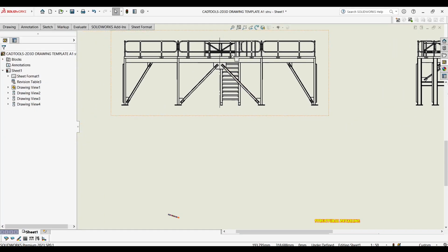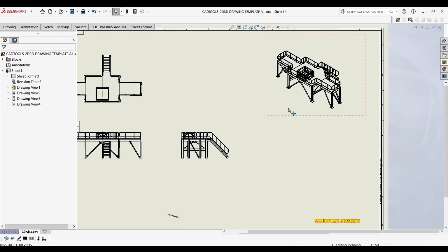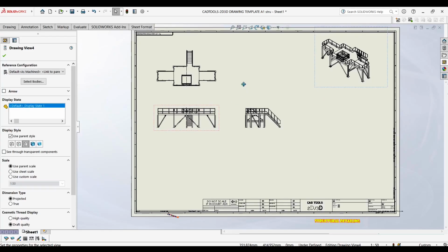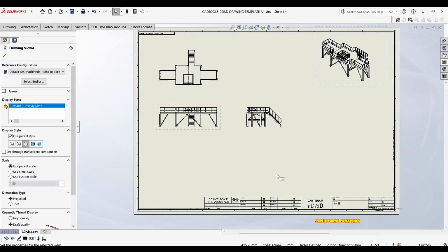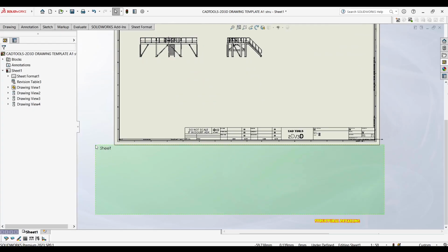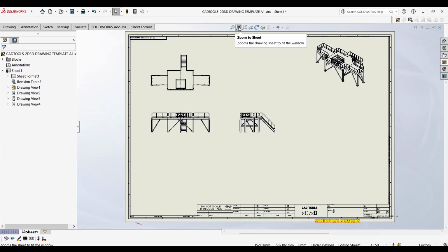and then guys, sorry if I became a bit louder, we have to now try to make these views a bit more visible. So with your mouse wheel, double click it. When you double click your mouse wheel, or you click here, zoom to sheet, it centers your sheet.